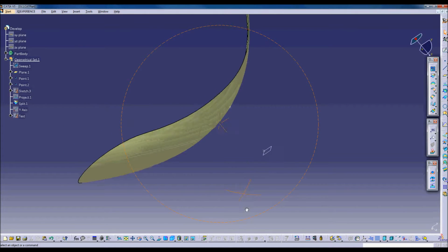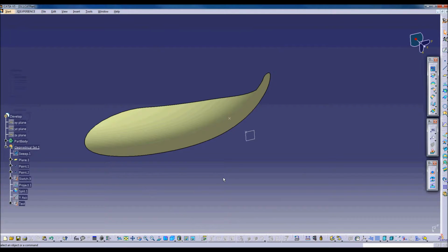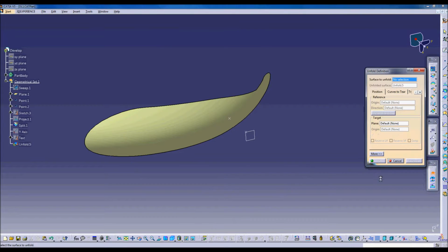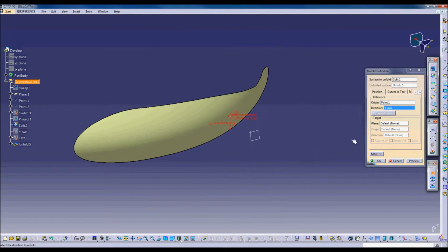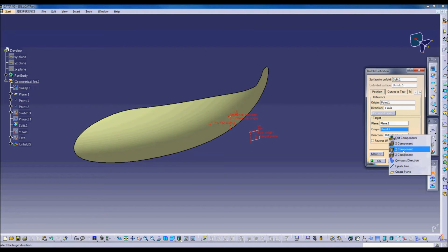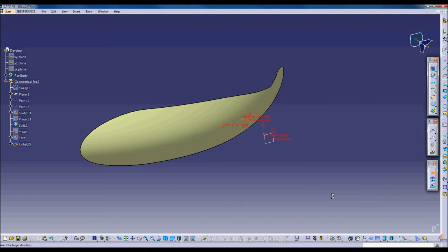You can see a double curved surface which I'd like to flatten. I select the Unfold tool, select the required geometry, the default assumes that the surface is ruled and that it is able to unfold without distortion. My surface obviously is not ruled, so I have to select All as the option.